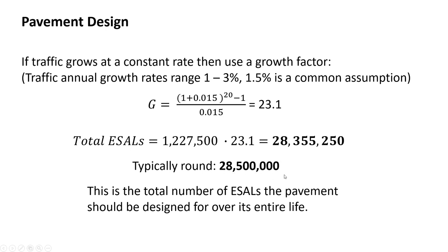Every time a truck goes by, it withdraws $2.50, or however many ESALs that truck is. And cars are withdrawing half a cent every time they drive over it, something crazy like that. And so when that bank account is empty, your pavement's done. You're just toast, right? You're putting a new pavement in. And hopefully you're doing some preventive maintenance over time, and you can extend the life of it and so forth.